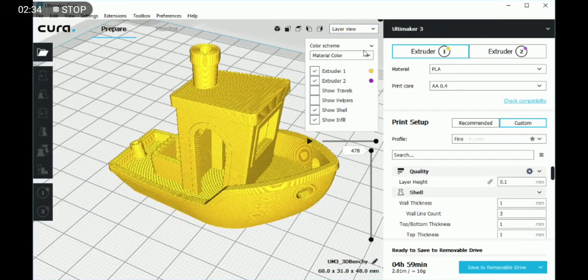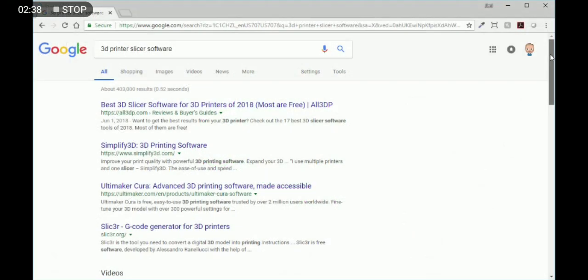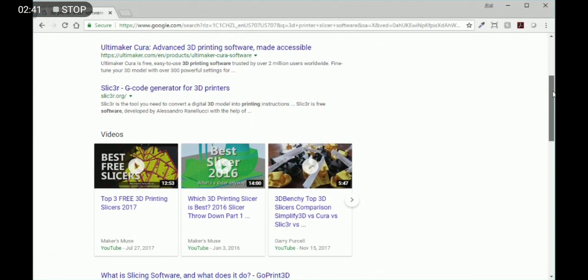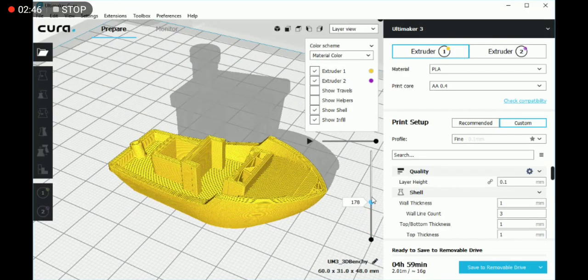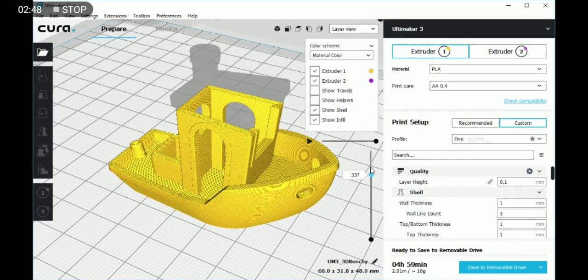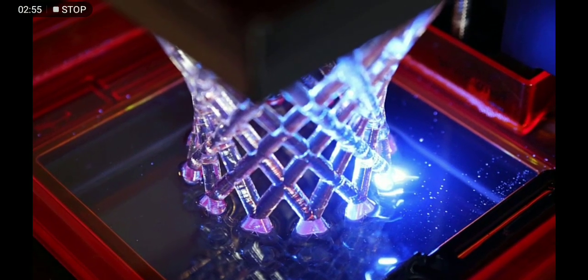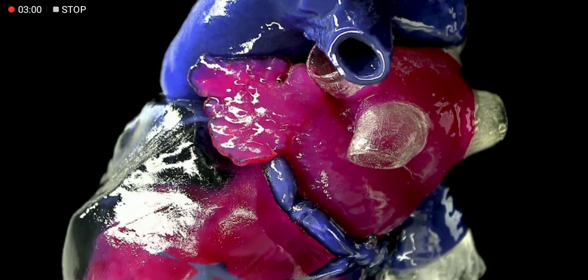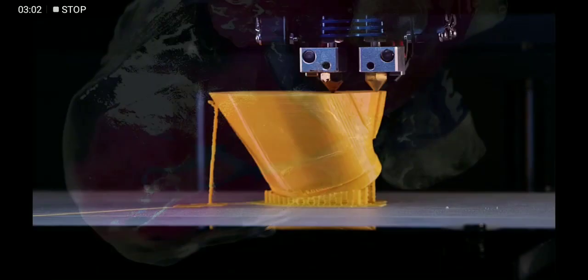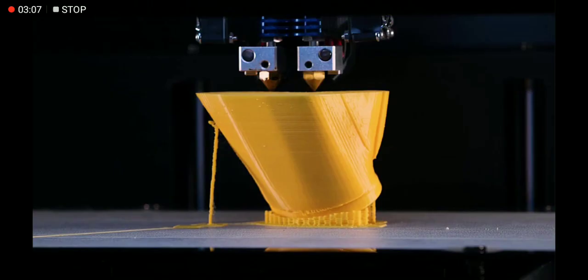CAM programs for 3D printing are also known as slicers because they generate 2D slices which are then stacked to create a 3D object. This can be done using a variety of methods when printed. Some use lasers to cure resin or harden a powder. Others use thin layers of ink-like materials to create full-color, high-res 3D prints, and others extrude plastic through a hot nozzle, like the FDM prints we'll focus on in this course.